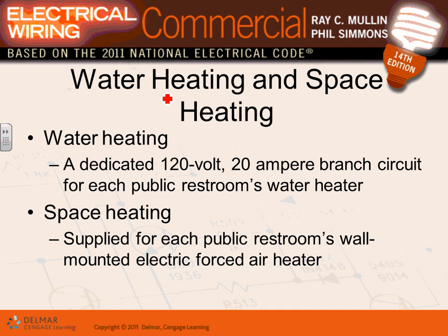Water heaters and space heating. Now remember, we're talking about public spaces. In all the public restrooms, they do have a water heater right there to get you domestic water. That's how they design it. So they have a 120 volt, 20 amp circuit, guys, to feed a water heater for the male and the female bathroom, so they can have instant hot water.